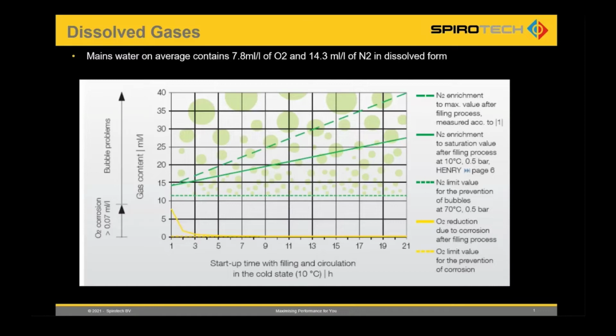They may get rid of some oxygen if it comes across it, but really, think about the time it takes from filling the system to doing all the balancing and getting it circulating and heating up. That length of time is probably longer than it takes for the chemical reaction of the oxygen to occur. You're not really going to get rid of the oxygen. And to be honest, whatever you've got for removing air in your system is potentially in the wrong place if you do add additional oxygen through the fill-up water.